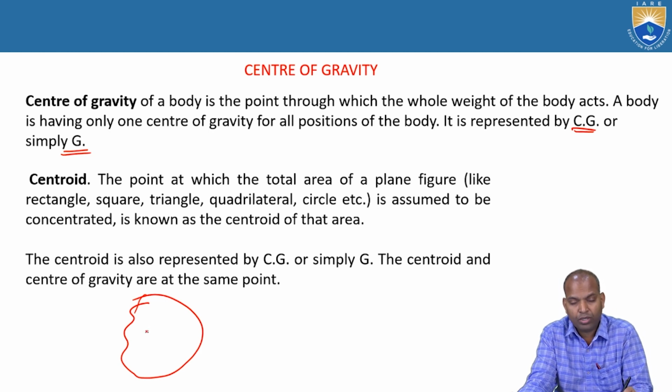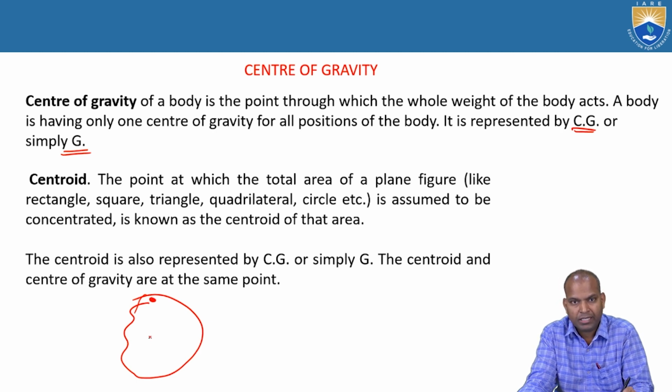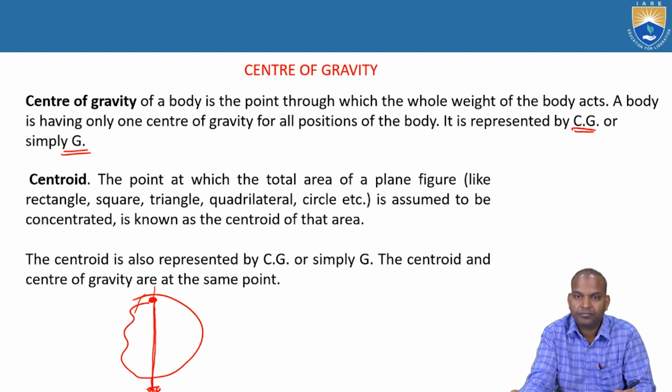If you want to find the center of gravity of an arbitrary shape experimentally, what do we do? We hang the shape from a certain point, and attach a rope or thread with some weight to that point. The rope hangs vertically downwards, and we draw a line.